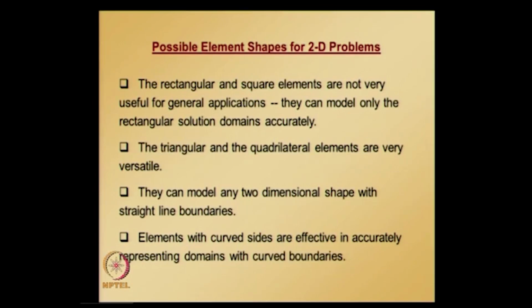So to start with, in this lecture we will derive triangular element shape functions, as the triangular element is the simplest to formulate, as it is based on linear polynomial trial solutions, which will become clearer when we actually start deriving the element shape functions for the 3 node triangular element.